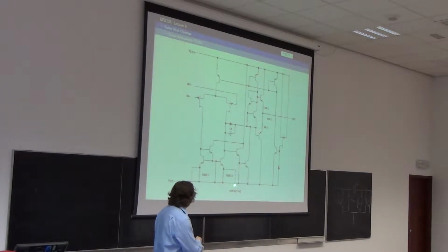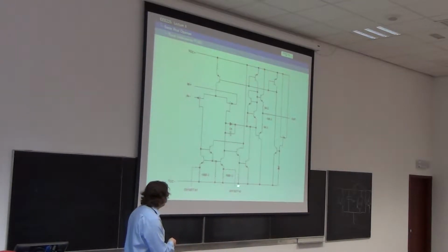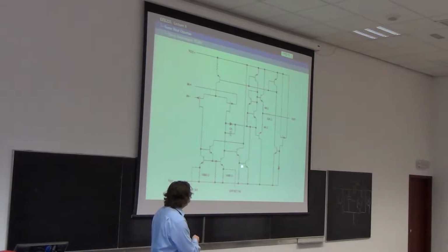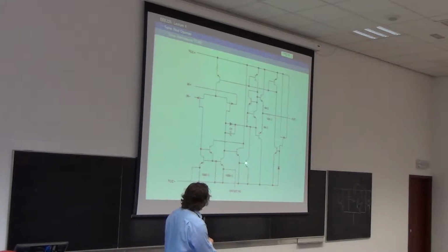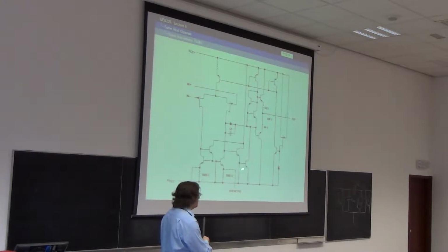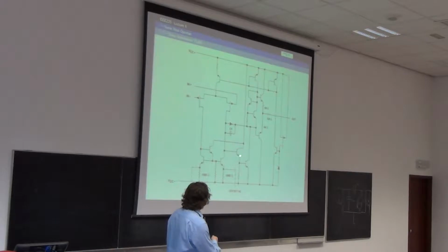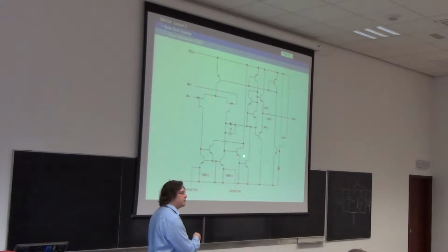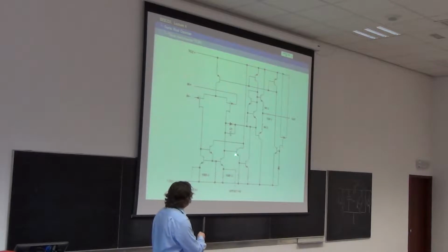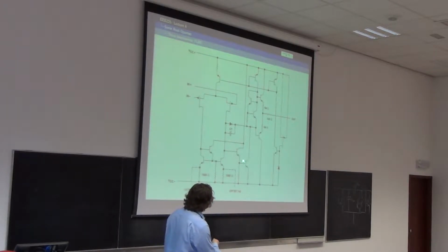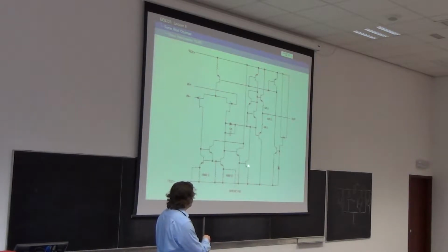You have to know what to think in this case, and what you're supposed to be thinking is, if I need to turn off this transistor, I've got to get all the charge out of its base region, because transistors are really a charge control device. If I'm going to get all that charge out, it's got to go somewhere. Actually, if we turn off this transistor, so the current down here stops, the charge in this base needs to escape quickly, and the best place for it to get out to is into the minus rail. So this resistor is there to speed up the turning off of this transistor.